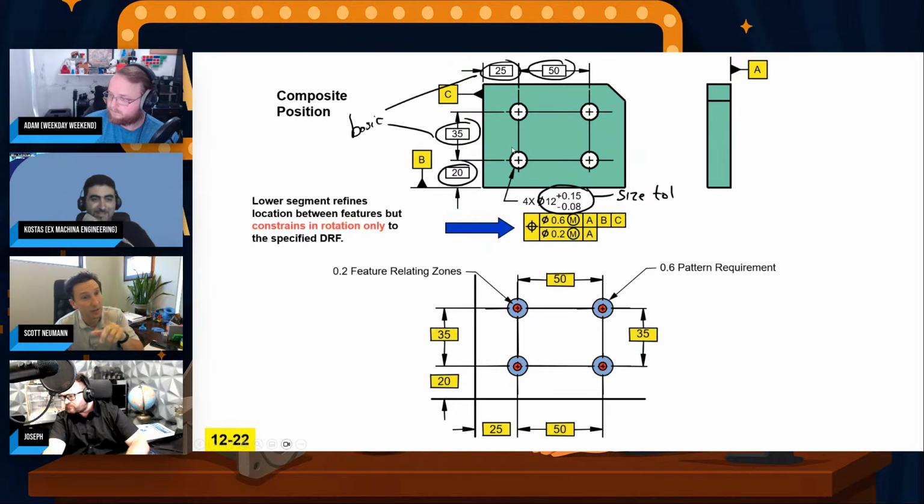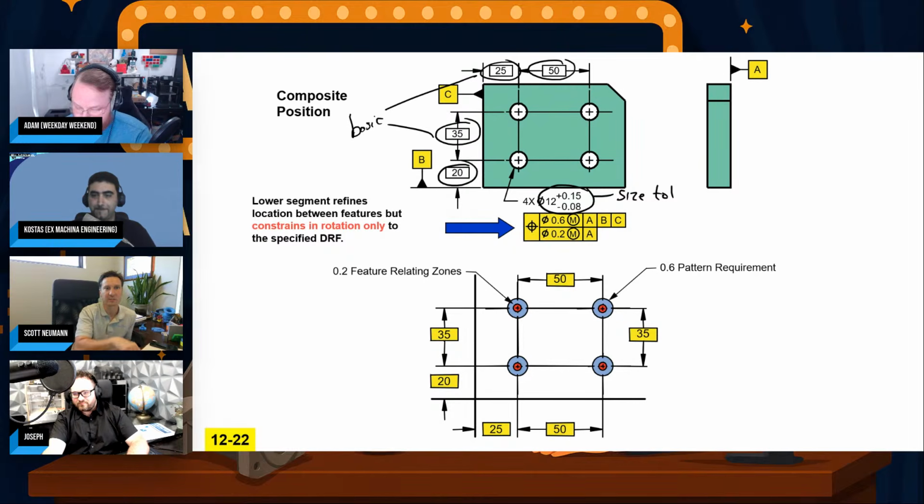Yeah, and it's been like that since 1982, actually. 1982 is when they first said, hey, you should use basic dimensions here. Stop screwing around with that plus-minus tolerance. But if you use both, it's a nightmare, isn't it? Oh, yeah, to actually check whether you're in spec or not. People think GD&T is in addition to plus or minus, but no, it's a replacement of plus or minus. Position and profile replace plus or minus. It's the successor to the older system. Yeah, exactly.